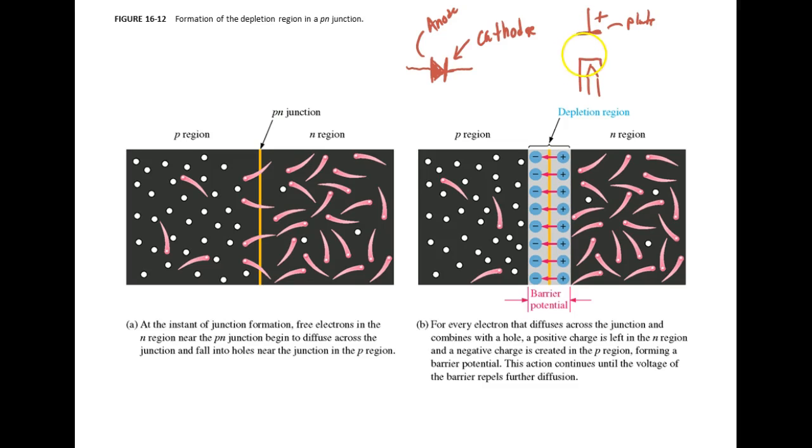When we heated up the cathode, it would emit all these little negative charges, and what would happen? They'd be sucked toward the positive potential. We'd make them go through little screen wires that we call a grid, and we would control the negative potential on the grid. If you got it high enough, you wouldn't let the electrons get through to the anode. If you started making it less negative, then you could control the current flow through that. So we can control the current flow with the grid.